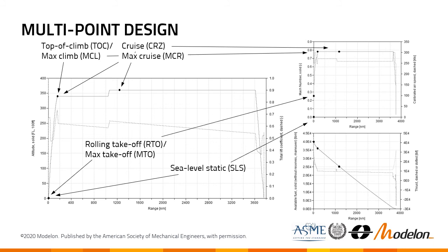However, it can be quite tedious to iterate between design and several off-design simulations. Multi-point design is then this natural extension to sequential classic design, where we are solving a design problem and several off-design problems concurrently with the same numerical solver. This also alleviates the need to manually track consistency between inputs and targets. They are simply formulated as residual equations or constraints.